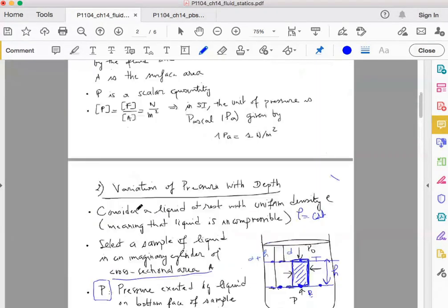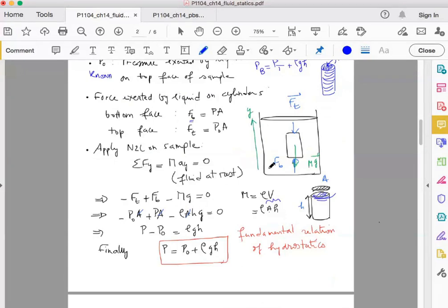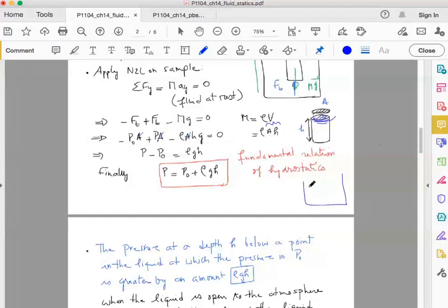Of course, from this section, all you need to know is that if you have a given container and a point at a certain depth, say you are looking at this container up into the atmospheric air. Number one, if the container is up into the atmospheric air, here I will call P0 the P atmospheric. So P0 in this case is P atmospheric. If the point is at depth H, you can say that P in this case is P atmospheric plus rho times G times H.